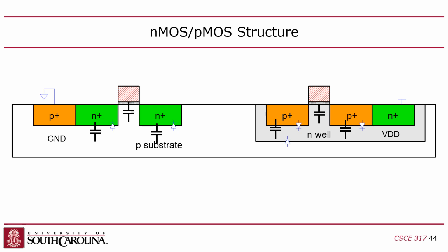So what ends up happening is that the charge carriers in this N get pushed away from the substrate, and the charge carriers in the substrate get pushed away. Because they get pushed away, it creates a kind of dielectric. It becomes the middle of a capacitor, right? So as I make the transistor wider, I get a bigger capacitor here, a bigger capacitor here, and a bigger capacitor here, right? So I really get a lot more capacitance with wider transistors.